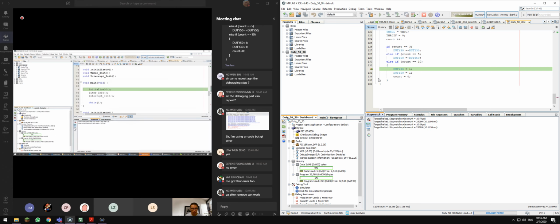Okay, my stopwatch, I click it to 0. Where's my timer initialization? Okay, interrupt initialization. I make sure that my interrupt initialization is on. Let's say I put my pointer over here. Okay, it's 100. Clear the thing. Take this off. Okay, so we come into here. It should be about 1 millisecond, which is correct.